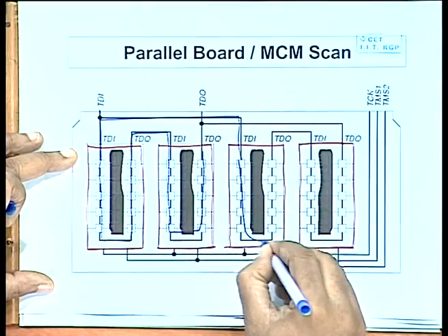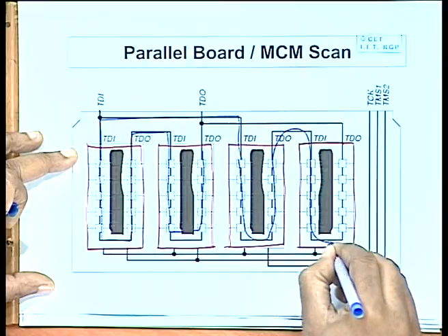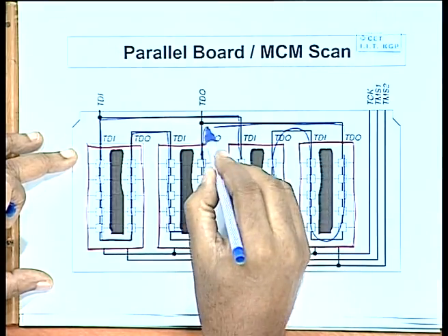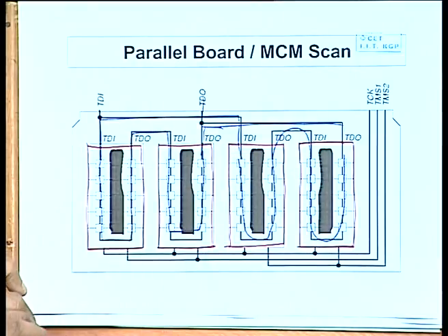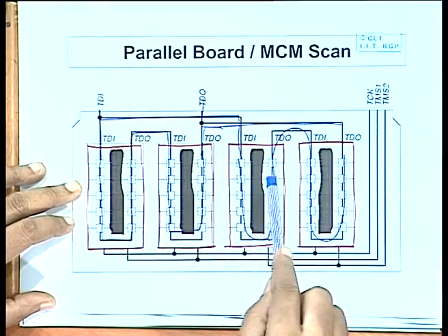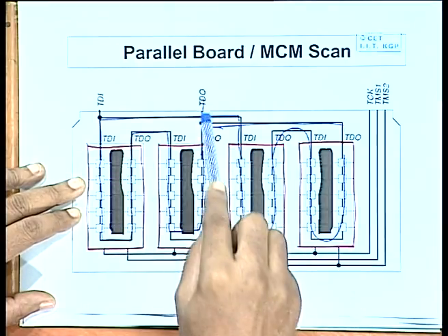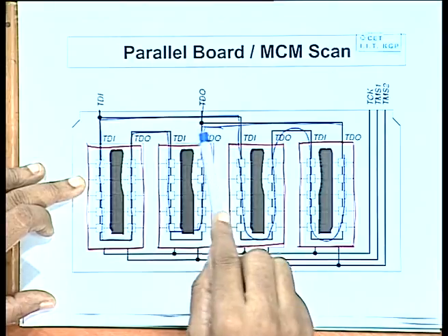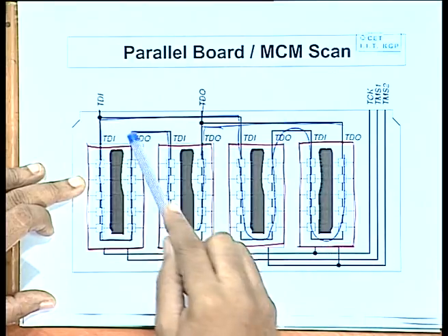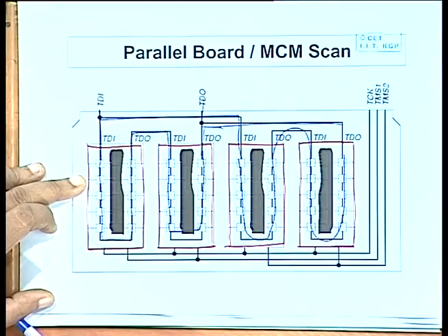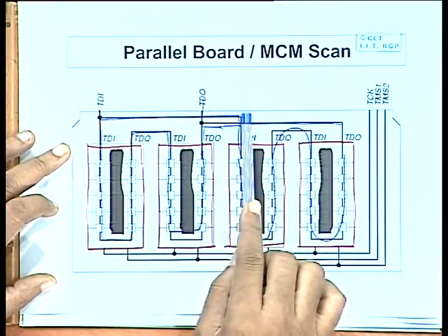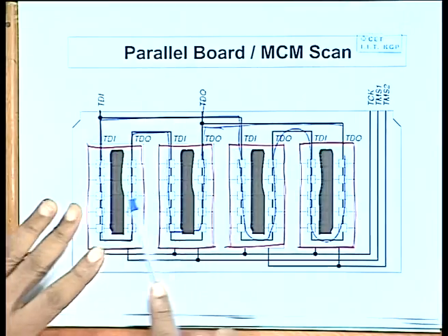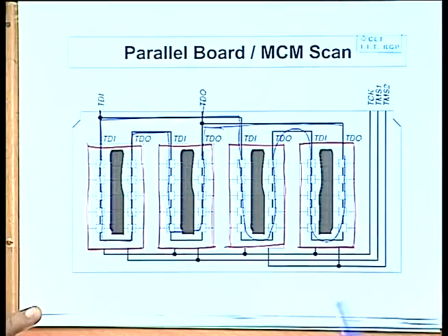Similarly, this one is flowing through like this. TDO is 1, they are all tied together. So, it says that you can parallelly test these two, but since you have one TDO, you can do it one at a time. But if you have two different TDOs, then you could have tested them together parallelly. Okay? So, it depends what kind of resource you have. You can have some chain together, you can have two blocks which you can do in parallel, and so on.